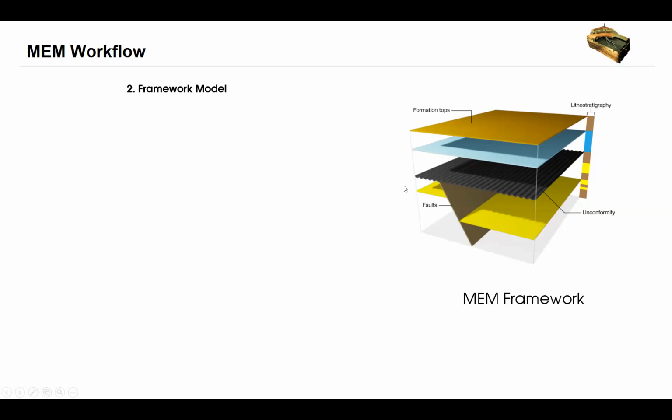If, for example, the rock were brittle at the time of the unconformity, it is expected that natural fracture intensity will increase approaching this fault, giving high natural fracture intensity here at this fault if it is brittle. Below this unconformity, the present day stress may correspond to the final stage of an extensional regime. But above this unconformity, this uniaxial strain condition may apply.